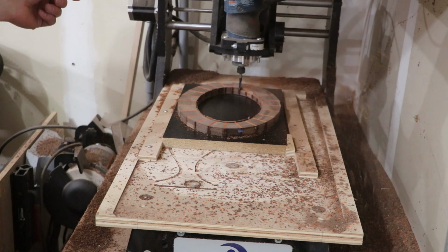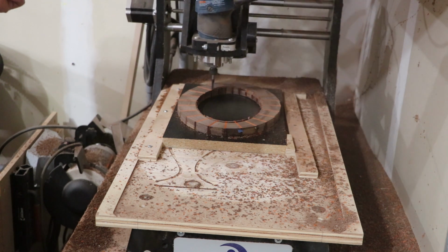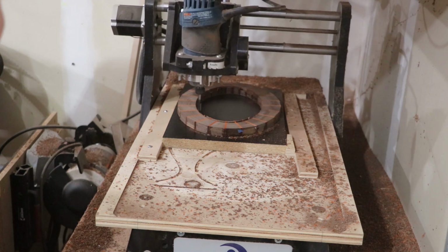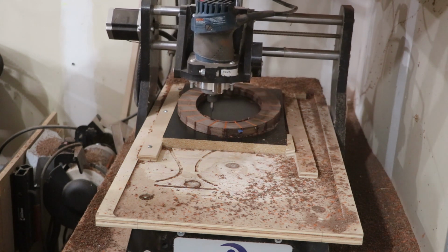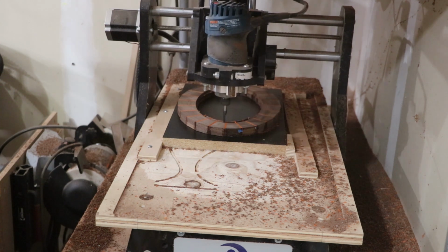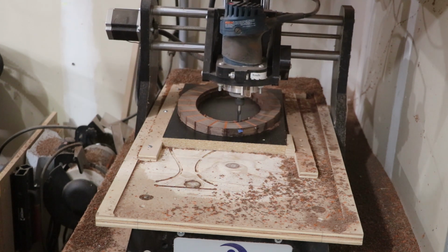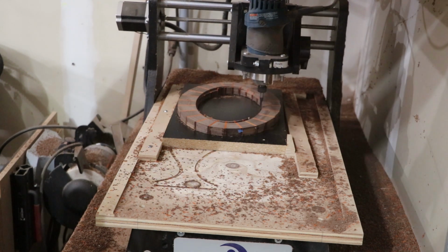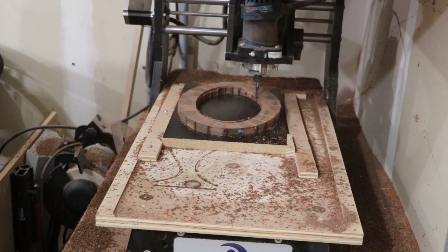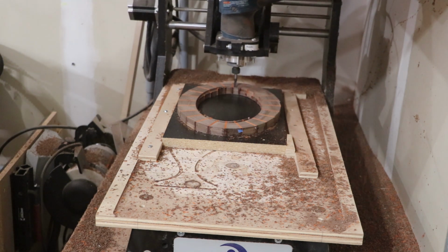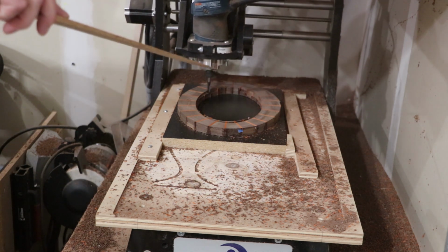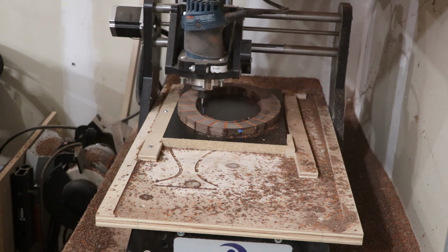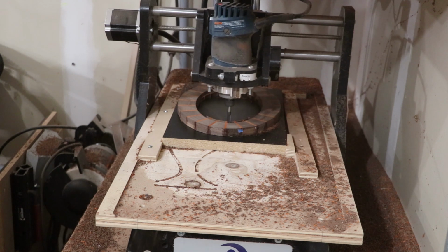To clean up the inside edge and to cut it to its exact final size, I plotted out that same speaker we used in SketchUp, and put that same oval as my center oval for the CNC machine, and just made sure I found the exact center of the oval and placed it as exactly as I could onto this double stick tape, taped it down to this black melamine, and then just used a CNC machine to cut it out on the inside groove and the outside shape. So it worked out pretty well.